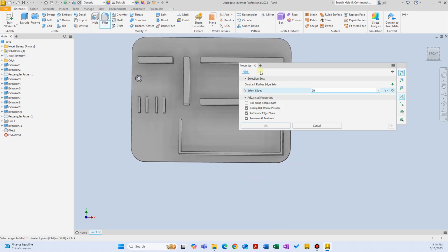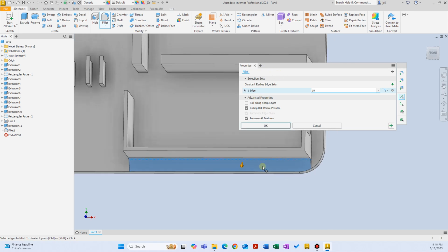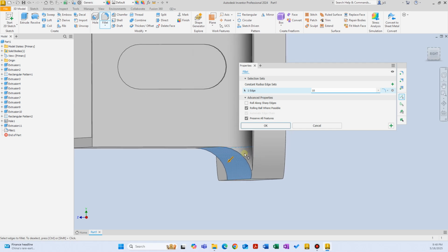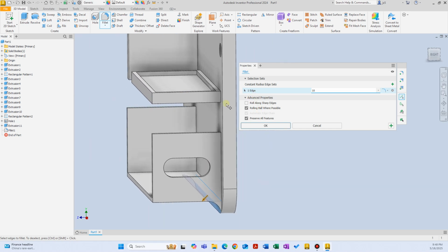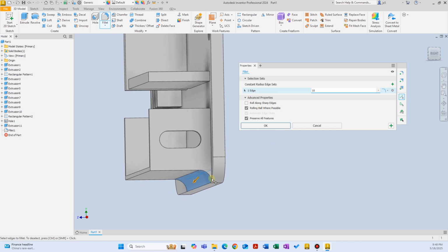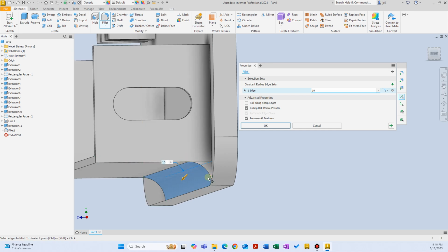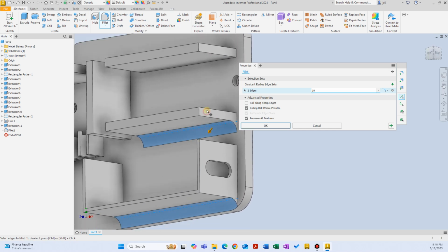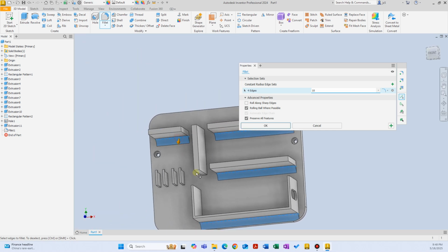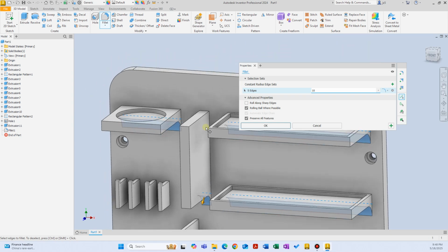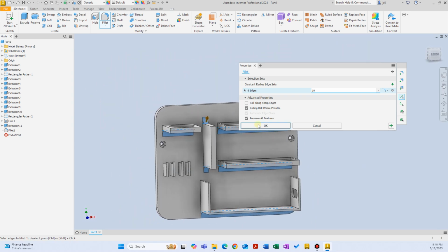So let's just start another fillet and enter 10 this time and use that to add material from the bottom, so we are making it a bit sturdy. We don't want these trays to break from these connection points, right? So let's use the fillets to add some material there and eliminate those stress points, eliminate those sharp corners by adding some radiuses there. So let's just do the same thing here, same thing here, same thing here, maybe even here. Yeah, let's just keep it that way.